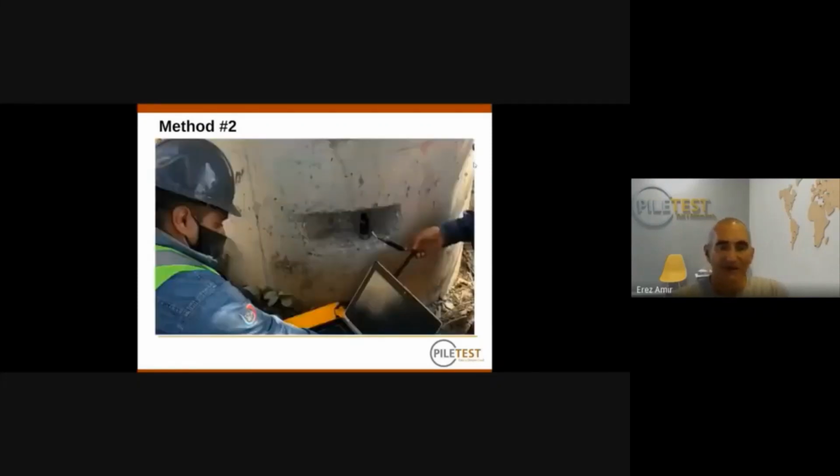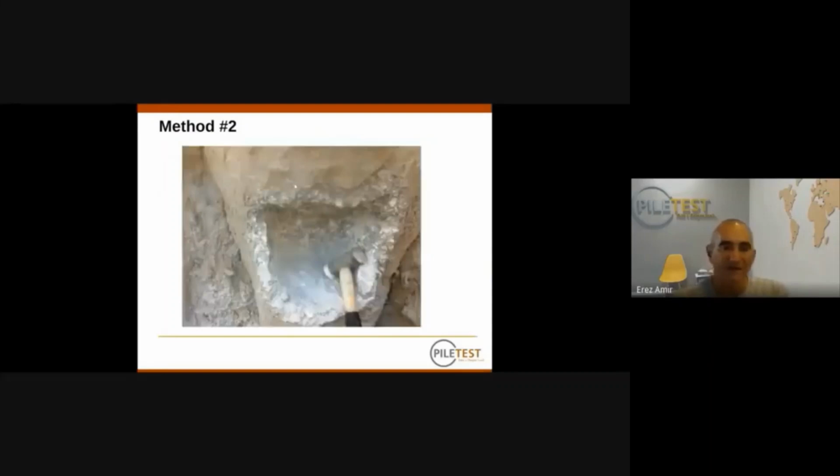Here's another example with the sensor inside, so you can see the side of the notch. It's constructively negligible compared to the size of this pile or column. And in another case, another pile in a retaining wall, and a small notch was cut there. You can see the hammer for proportion. This gives you the good option for testing with the pulse echo method.